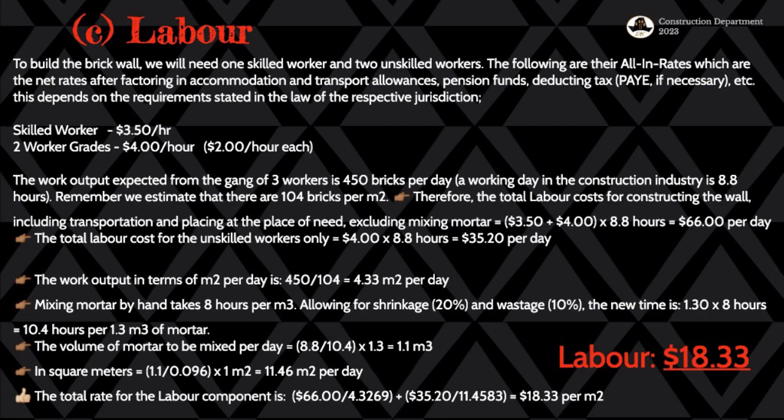That's another standard that we need, because we are now going to calculate the hours that need to be used, or that need to be considered when we have that mixing of more concrete than usual. We're expecting the concrete per cubic meter, but we then have that extra 30% that we've added due to shrinkage and wastage, which means that it is more work, so we need to increase the time.